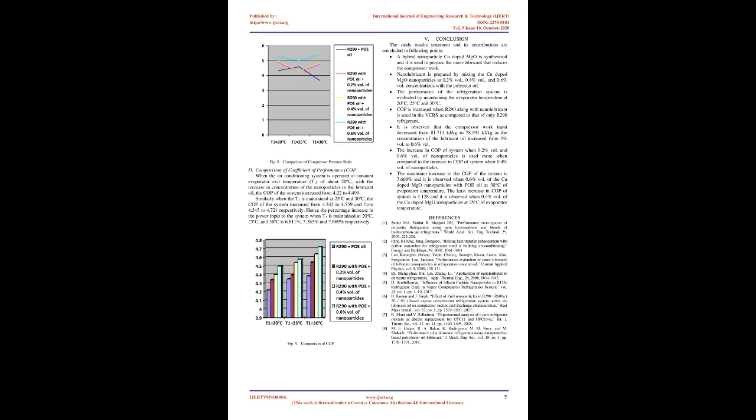COP is increased when R290 along with nano-lubricant is used in the VCRs as compared to that of only R290 refrigerant. It is observed that the compressor work input decreased from 81.711 kJ/kg to 78.591 kJ/kg as the concentration of nanoparticles in the lubricant oil increased from 0% vol to 0.6% vol.